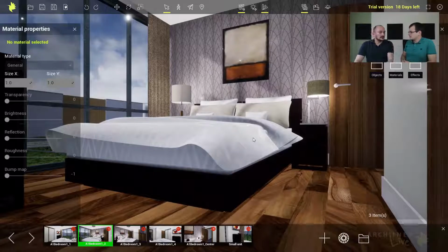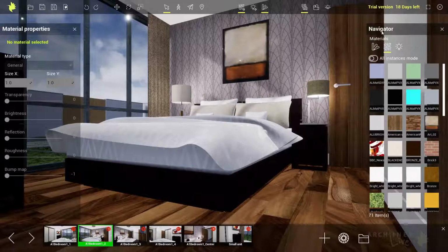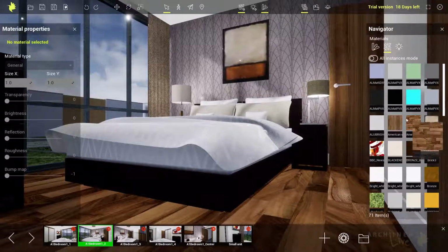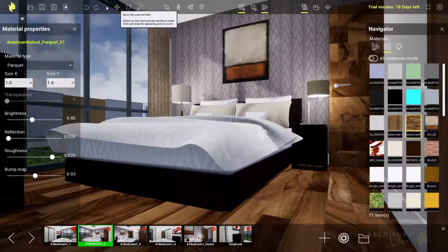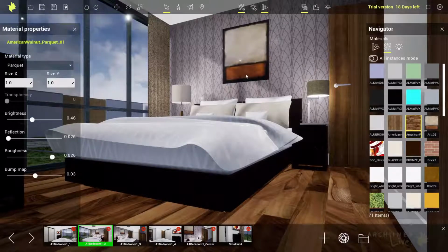Talking about what you just mentioned, there is a list of those materials in Navigator. Those materials came with the model, as you can see in this panel. All the paint and wall surfaces and everything else are collected here, so you can just click and drag and use them on the surfaces at any time. Let me find something, for example this one. If I just drag it, well, that's the same material. So let me change it here. It's just changing. This is how you can easily reuse those materials on all the other surfaces.